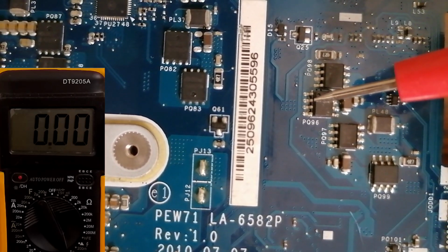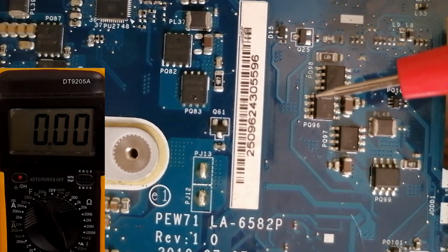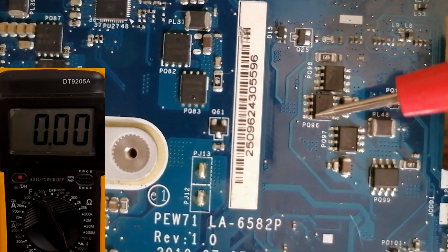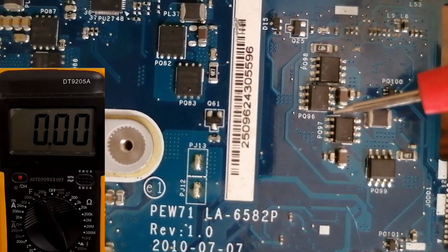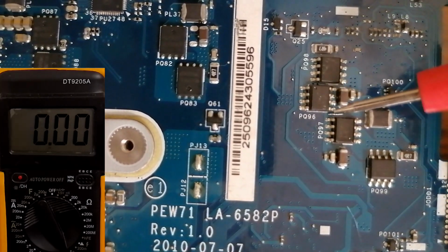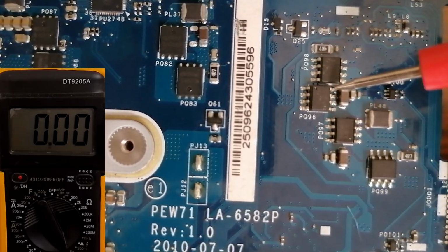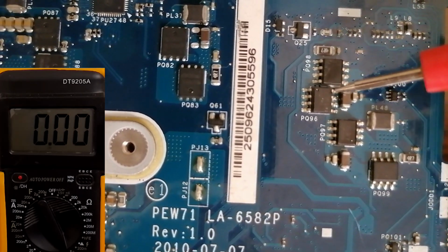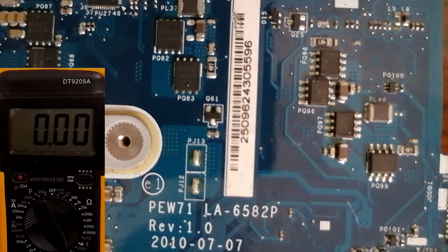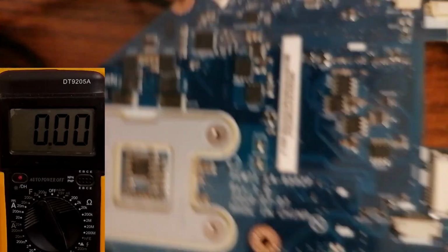number 1, pin number 2, pin number 3. So this is source, and pin number 4 is for gate, and here we have 4 pins for drain, 5, 6, 7 and 8. So if we check these pins, we should find 19 volt, exactly as we have in the schematic. So let's see.